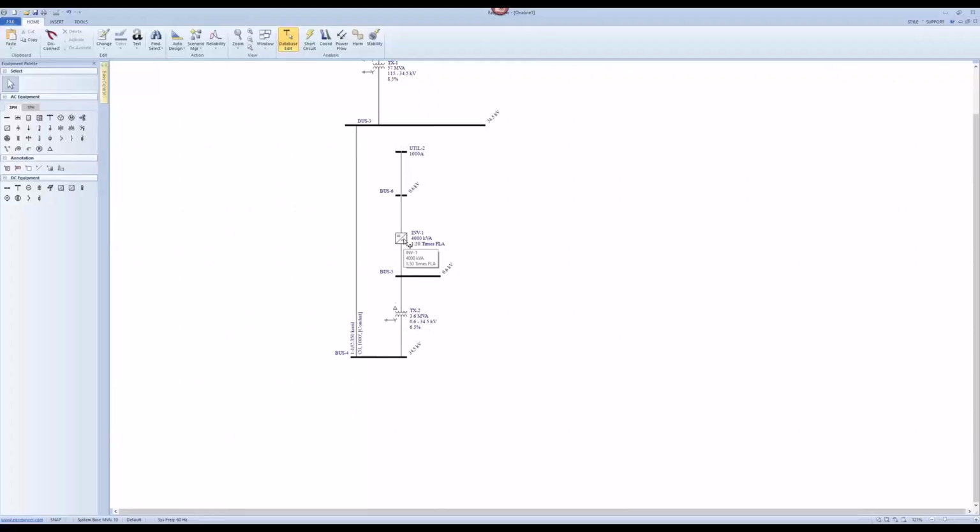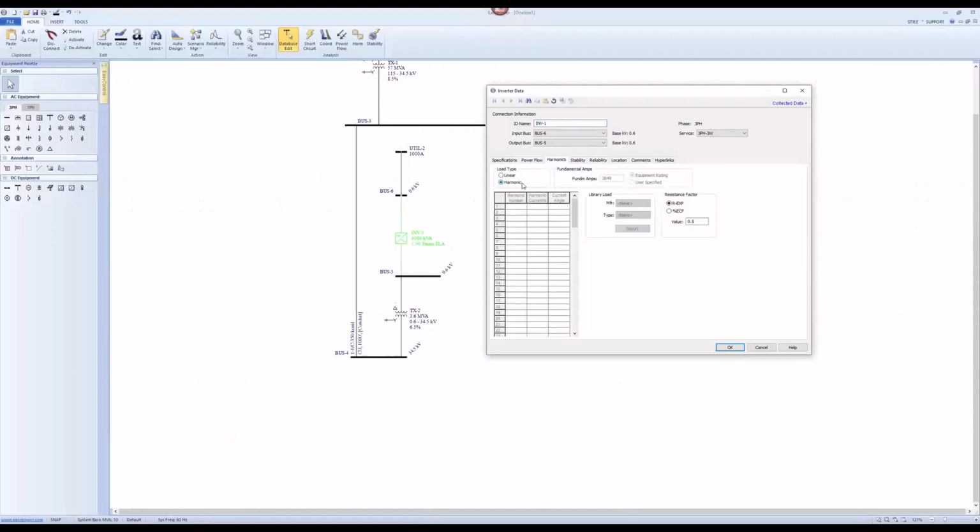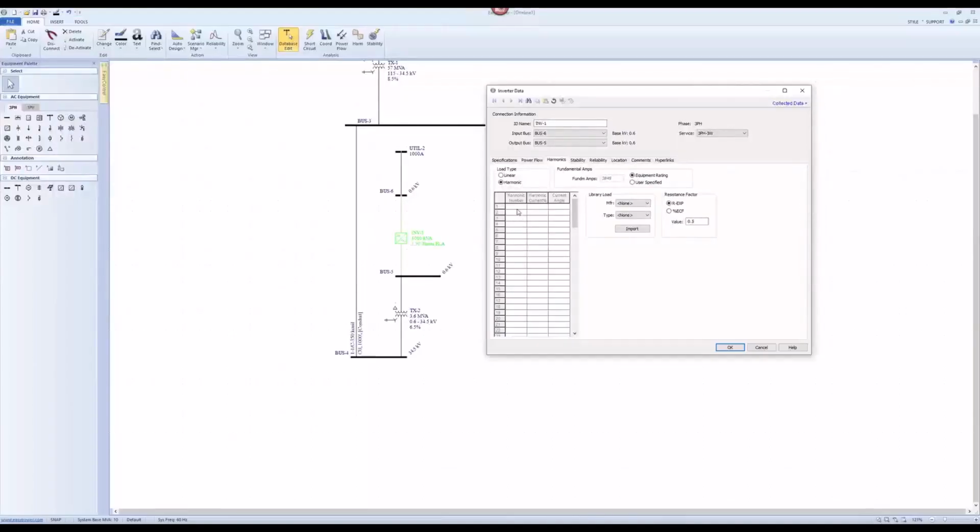So it's a good habit that you build the full model of the inverters and the system in EasyPower and then start copy pasting and those fun things. So let's enter it. I know that my harmonic source has been calculated by my Excel spreadsheet, which is here. So I just copy, paste it here.